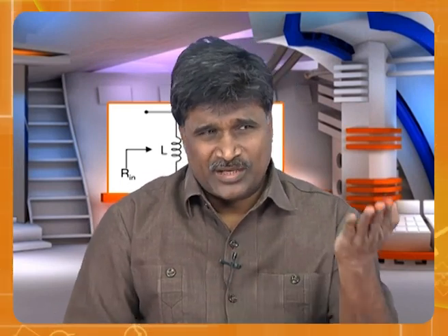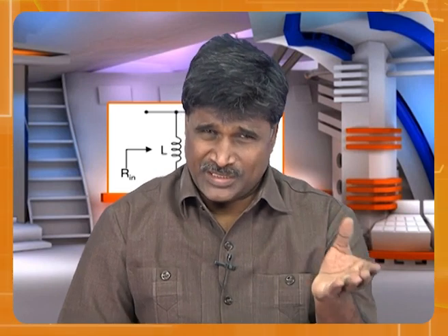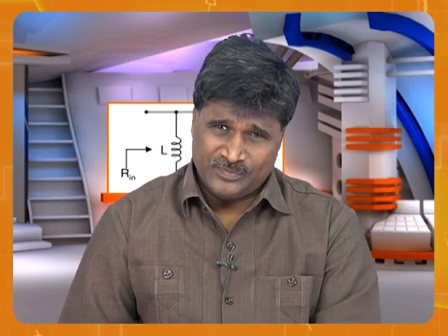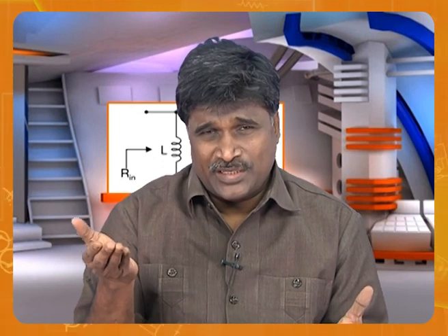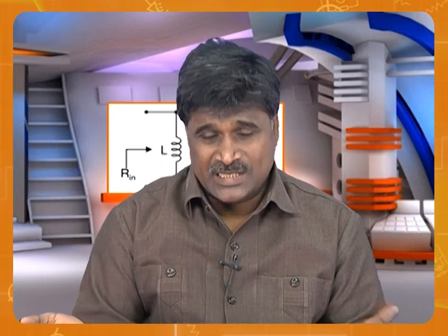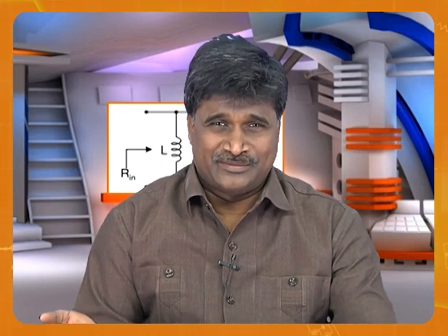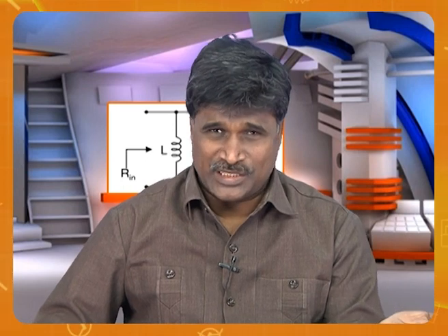So now I am concluding in 2 sentences. If you are analyzing, as much as possible go with inspection method or direct method using initial value, final value. If you want initial and final value also, physically. Therefore, what is my conclusion? Calculate the initial value, final values from the circuit and substitute them in the direct method. You will get some questions on initial and final values, some questions on calculating the actual expression.